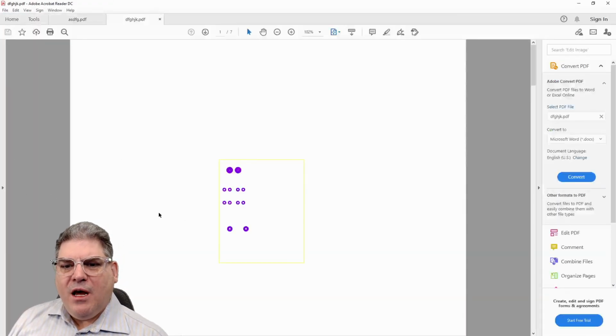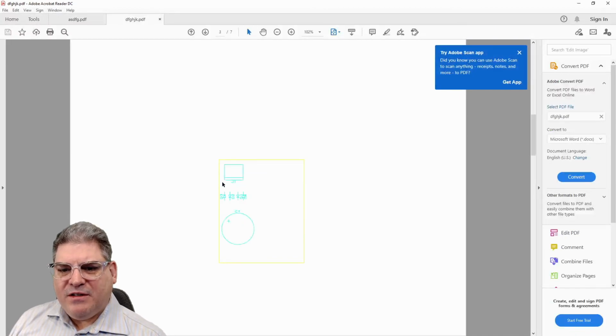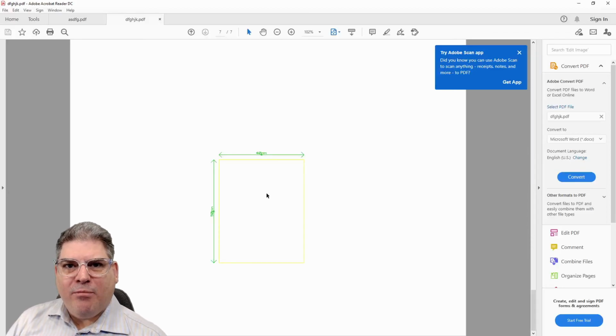You'll notice that each page of this is actually a layer. So here's my top copper, my silk screen, my bottom copper, and the board edge is shown on each of the parts. This is a great way and makes it super easy for me to look at your PDF print, and it would be appreciated if you did follow this for any PDF prints of your PCB.